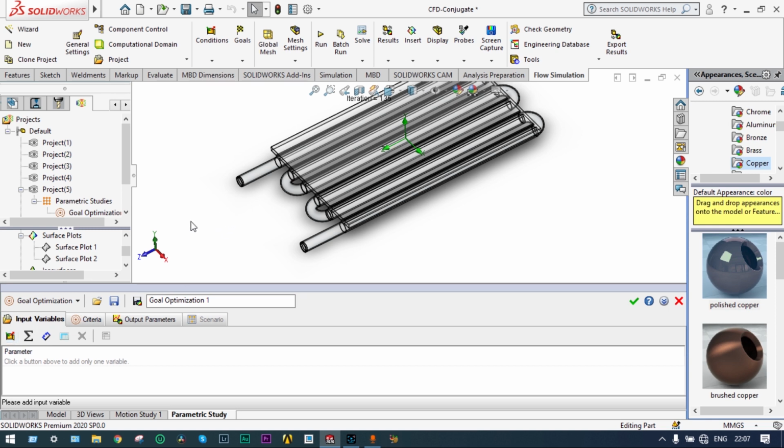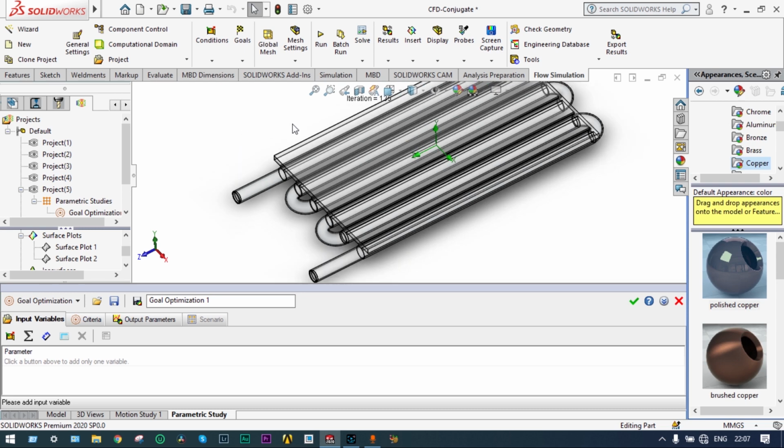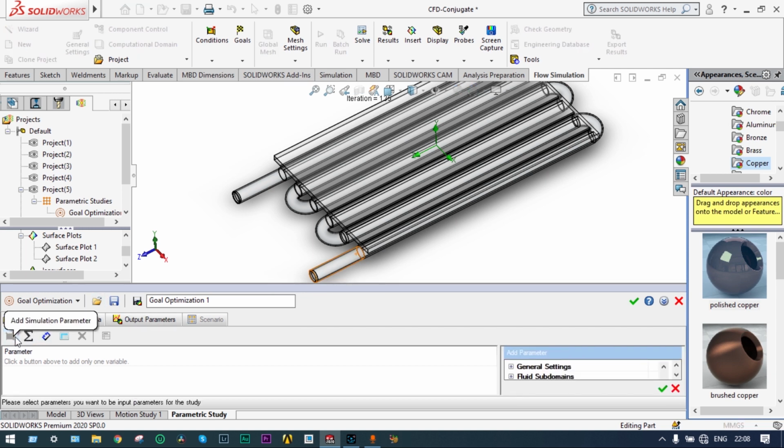Here in this case, we feel that input variables will be better for optimization. We want to reduce the maximum temperature of fluid from 129 degrees centigrade to 100 degrees centigrade. So for reduction of temperature for this freon, we want to provide more cooling with more mass flow rate, right? So we're considering these variables from here.